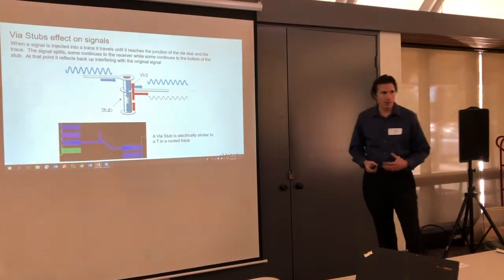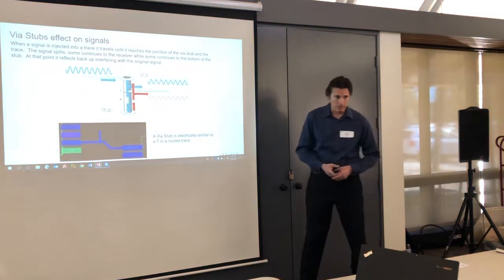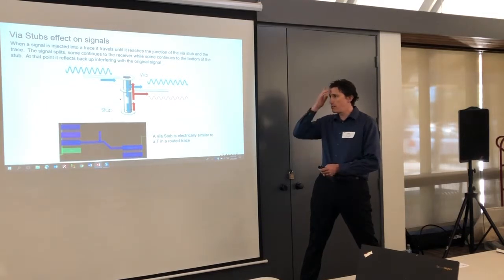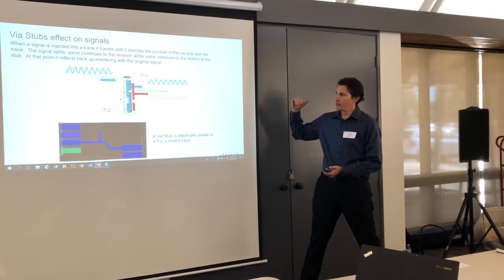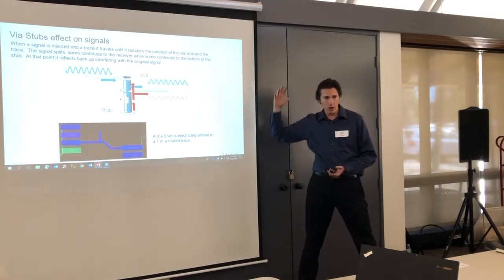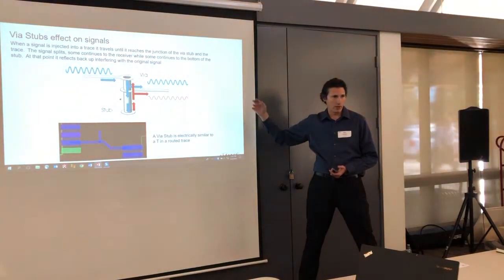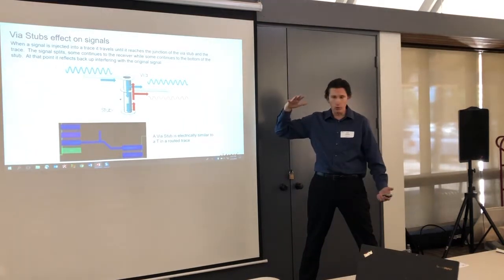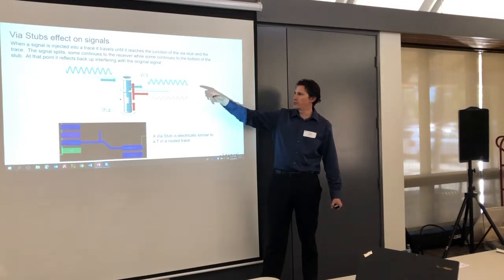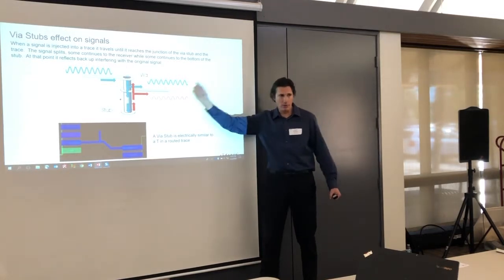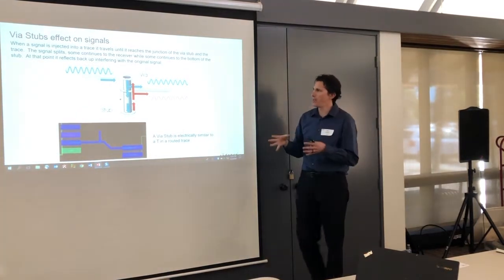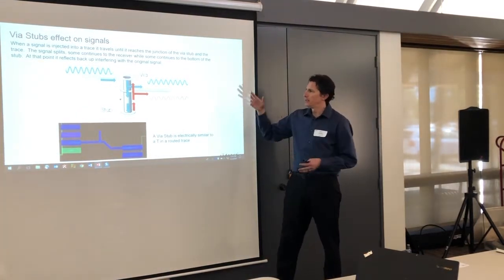So, first thing I'm going to talk about is back drilling. Probably a lot of you have already heard of this, probably a lot of you do it, but the reason you want to consider back drilling is if you have a through-hole via going from the top of the board all the way to the bottom, on a multi-layer board, 4-layer, 6-layer, 8-layer, this gets worse the more layers you have in your design. And if you only route that signal out on the second layer from the top, go all the way across your board and then back on the top, what happens with the energy of that signal when you shoot that into that via?